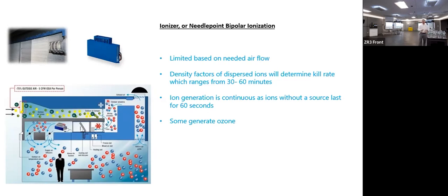In fact, it actually adds additives and it has effects where it can spike the level of different types of pollution, but also play a significant negative role on your overall health. If it's deactivating microorganisms and cells, what do you think it's doing to us when we breathe these in? So negatively and positively charged ions, needlepoint bipolar ionization, can work in the proper setting where you want it to be at the source of contamination. It should never be used as a room cleaning device or an air purifier. It doesn't purify. You're adding additives.